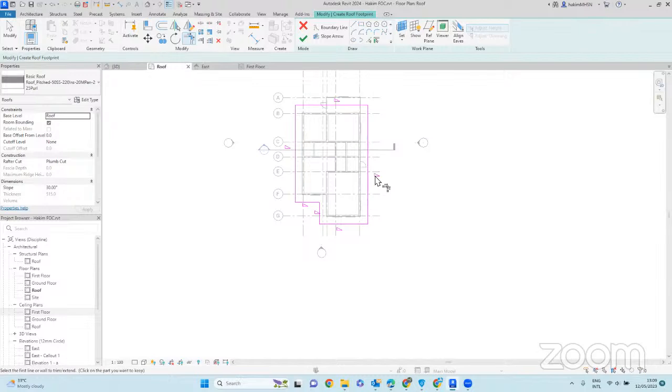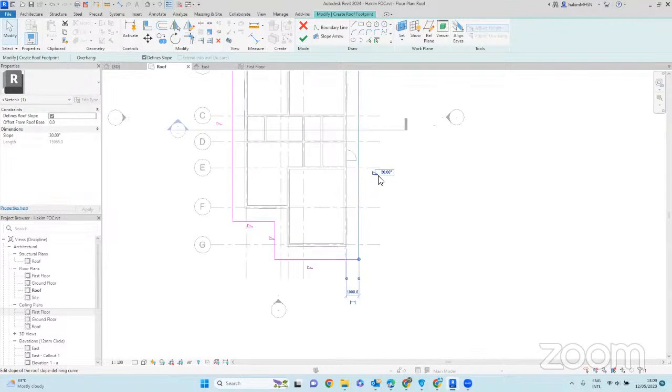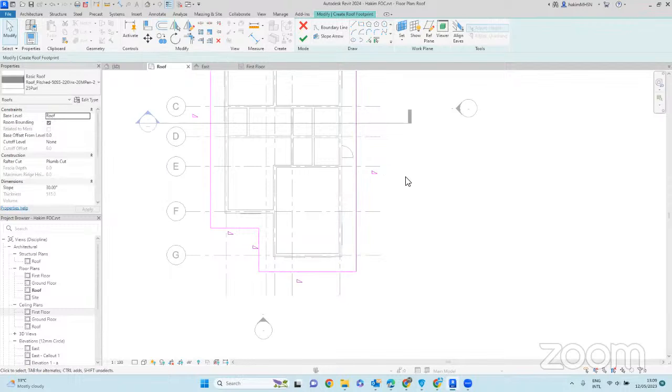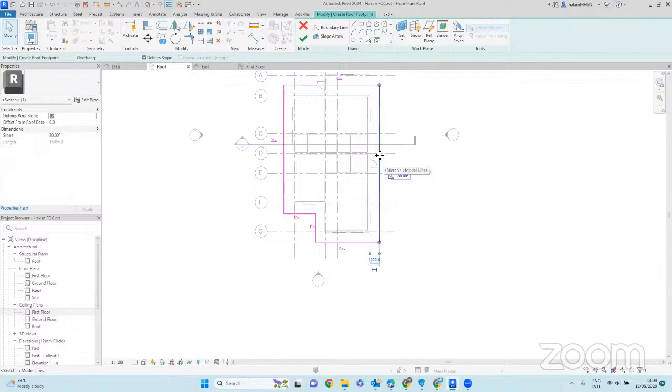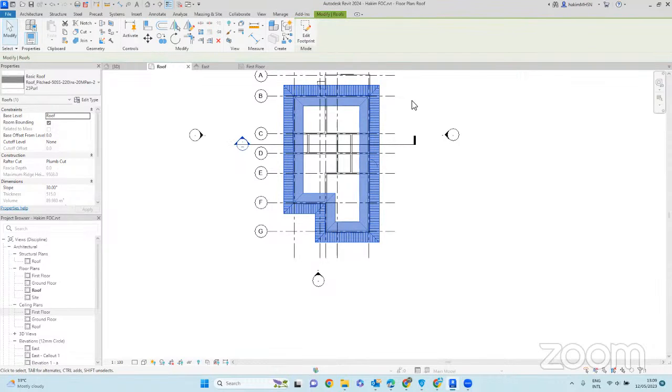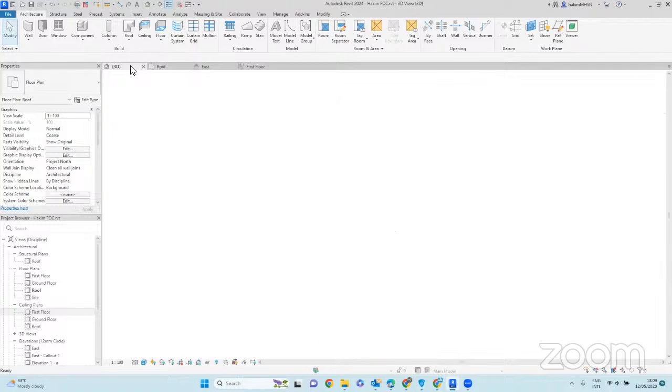This icon shows that this side would have an angle, and that value will be 30 degrees. It's not necessary that you have angles on every side, but for now, I'll just leave it as it is. Okay, and then I click finish and go to my 3D view.